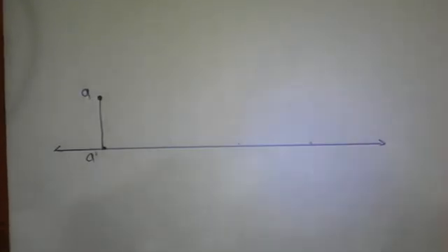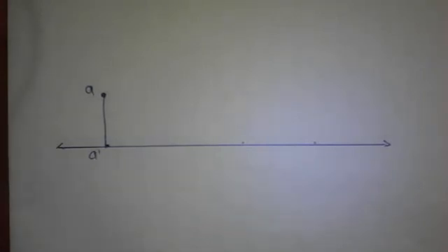This is A. Point B, which is below HP and 25 mm behind VP, means it is behind, so second or third quadrant, and below the HP, hence it is in the third quadrant.